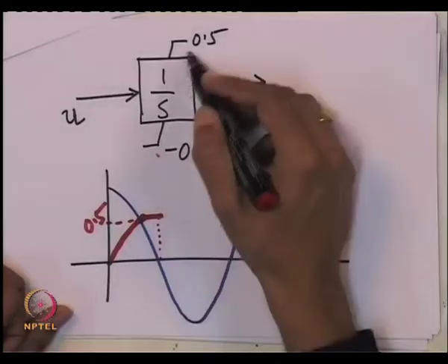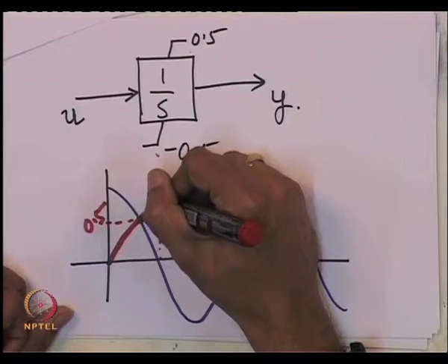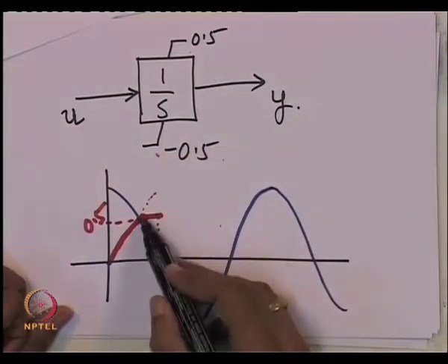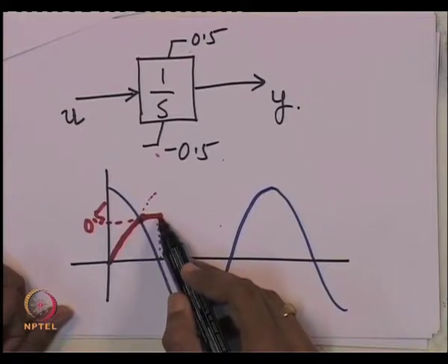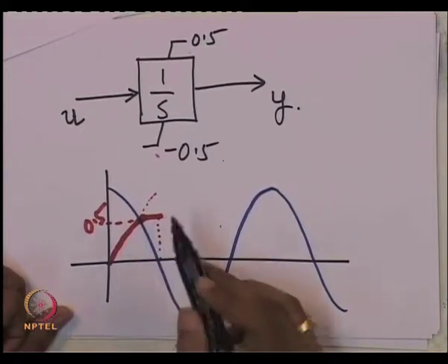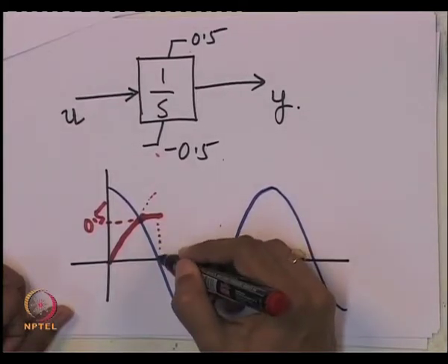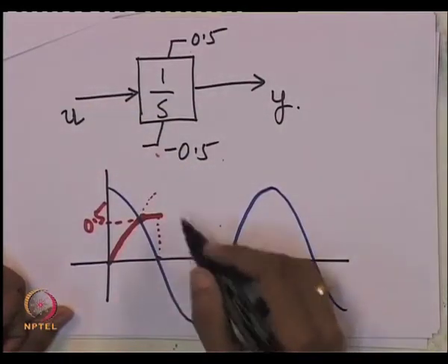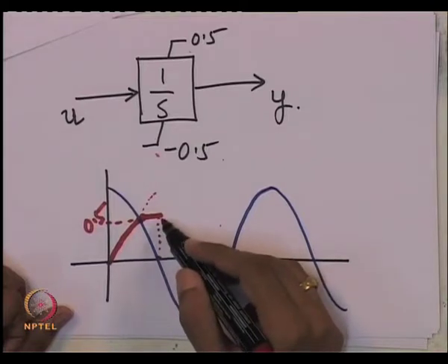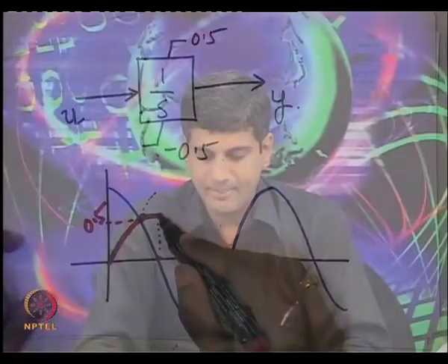So, what happens is that the integrator itself stops integrating. It is not that the integration is going on. At this point, we do not continue with the integration. We stop the integration and the output remains at this value. This is exactly as we got before, but whenever the integrand, this is u, the input becomes negative, there is a chance of coming out of its limit, okay? Because if you integrate a negative quantity, then you start decreasing from where you are. So, what will happen is you will come out of the limit right away.